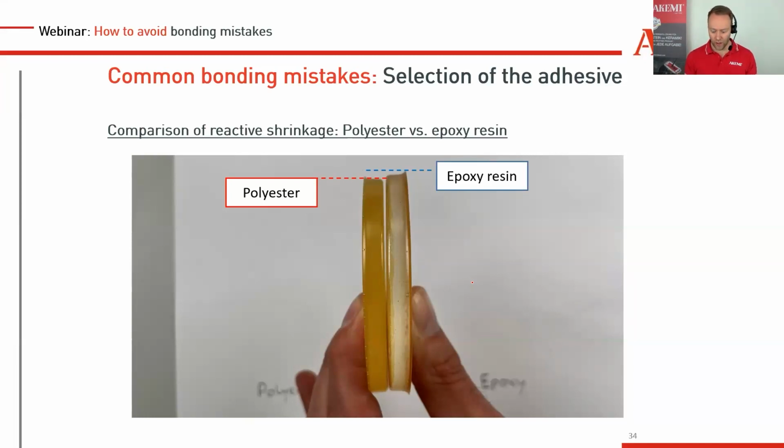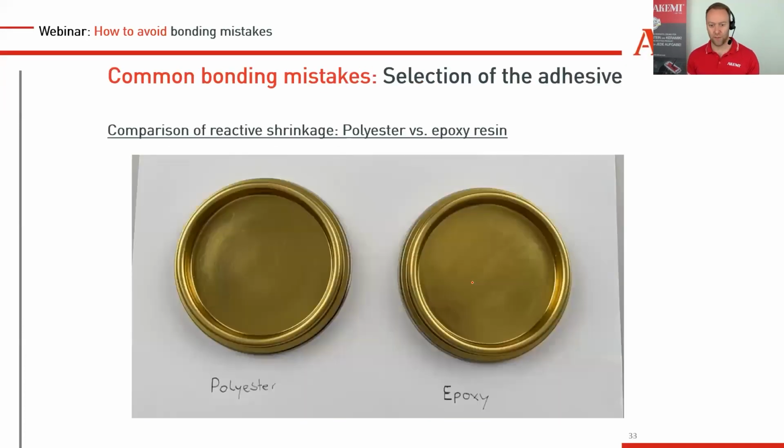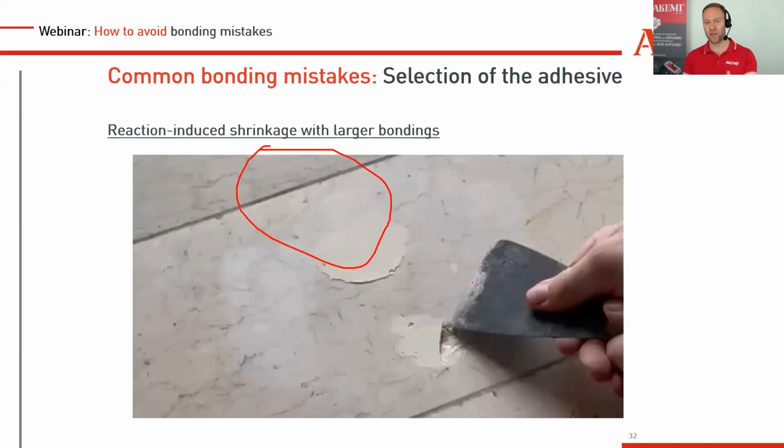Yeah, generally, when it comes to this big filling of holes, even if you use epoxy, what we always recommend is, also because it looks nicer: when you adapt only by color, of course you can adapt the color quite well, but still you have lines and you have stone structure. So what we always recommend, use as much crushed stone as you can to throw into the glue. Doesn't matter if it's polyester or epoxy.